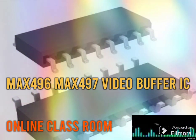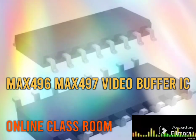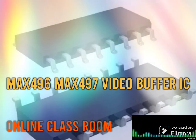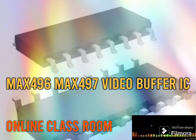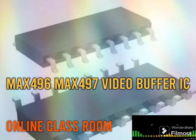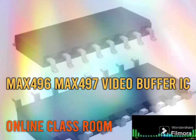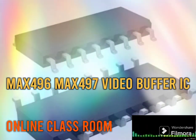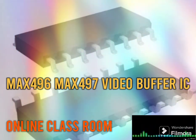Today's topic is the study of max496 and max497 video buffer ICs. The max496 and max497 operate on a plus or minus 5 volt power supply. They have a high bandwidth and slew rate, making them suitable for both component video and composite video signals.